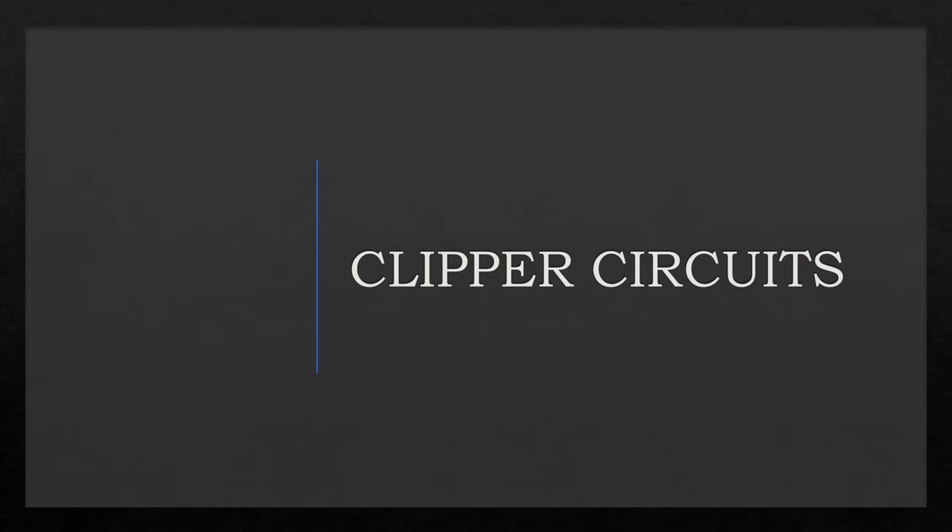The half-wave rectifier is an example of the simplest form of diode clipper, one resistor and a diode. Depending on the orientation of the diode, the positive or negative region of the input signal is clipped off, which is also known as diode limiters.